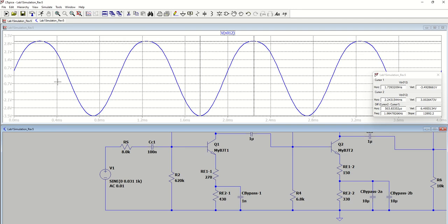It's kind of touch and go, going back and forth and playing with it. So I would say there's a tiny bit of linear distortion, but this is probably the maximum output you're going to get before it starts clipping. So increasing the input signal to get an output signal that is not clipping, our max output swing would be 6.49 volts peak to peak.